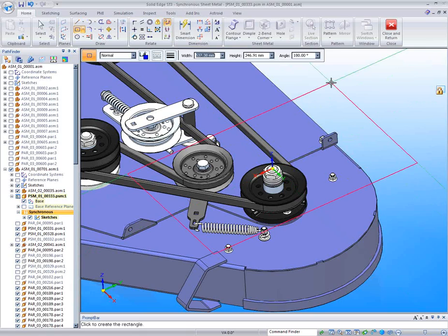But notice up at the top of the screen, this particular piece happens to be in metric, which is fine, but up top it's looking for my dimension. So my command line up there is looking for a dimension. I can do that just as well just by typing in. For instance, I want this 190 by 200. I'm going to hit tab, and then I'm going to hit 0 for the angle, and it's going to go